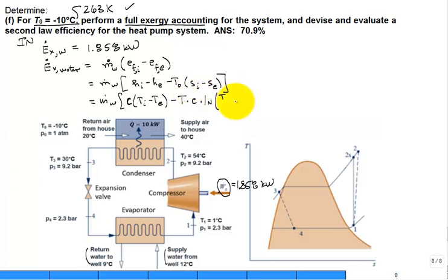You're doing the temperature inlet divided by the temperature exit, just like that. If you had S2 minus S1, it would be C natural log of T2 over T1. Just make sure that this one pairs up, and then this subscript pairs up. That's all. Even though it is inlet minus the exit, some people may want to put the temperature exit divided by temperature inlet, but don't do that. This is the correct one. So we have 4.2.